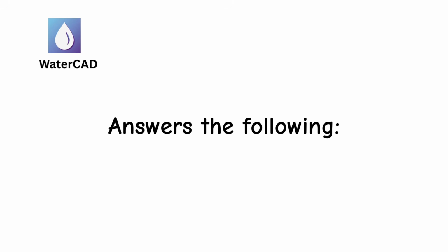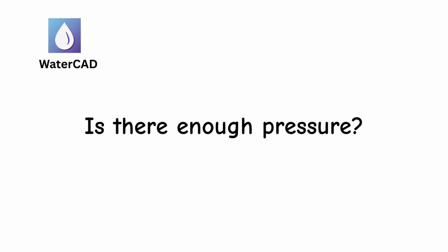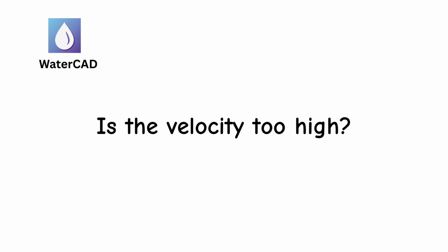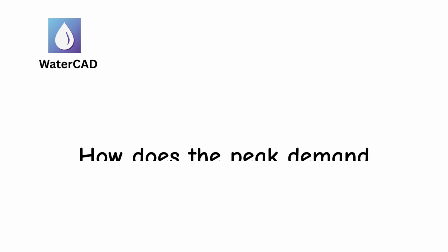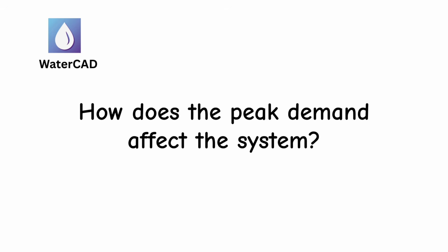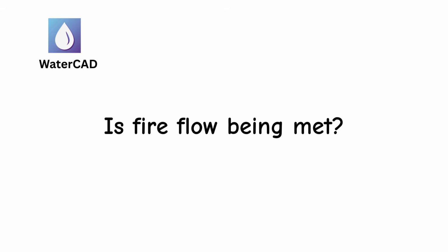WaterCAD helps answer questions such as, is there enough pressure at this location? Is the water velocity too high? Is the pipe large enough? What happens when several buildings use water at the same time? And can the system provide enough water during a fire?